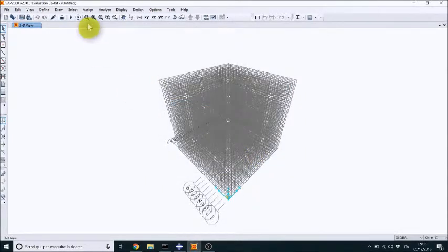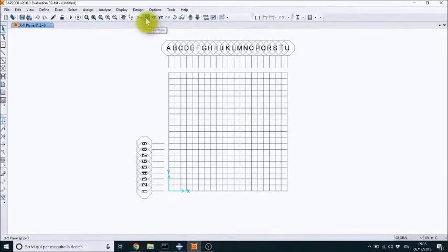Okay. Now we have to design the three-dimensional mesh starting from a shell mesh. You can see at the bottom your different positions along the Z direction if you are in the XY plane.